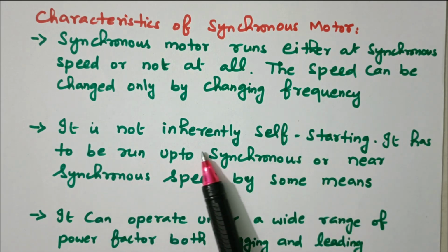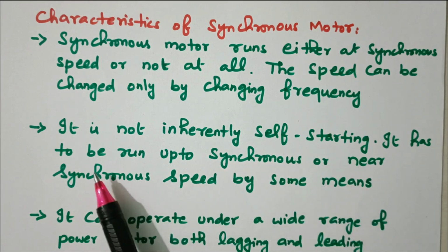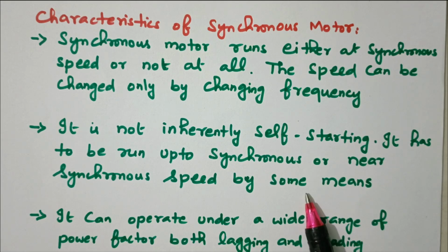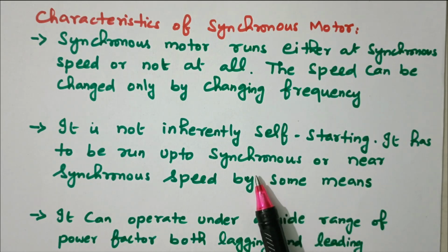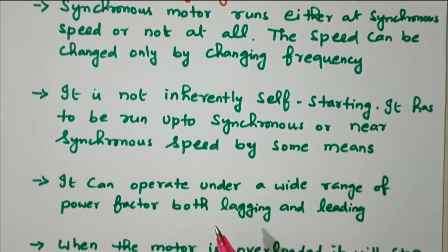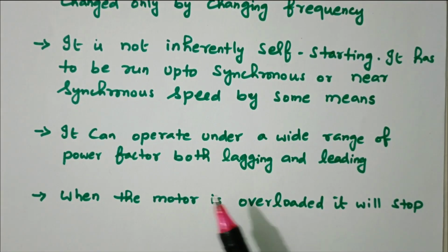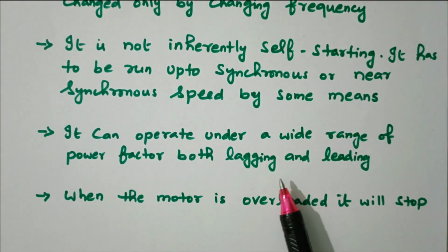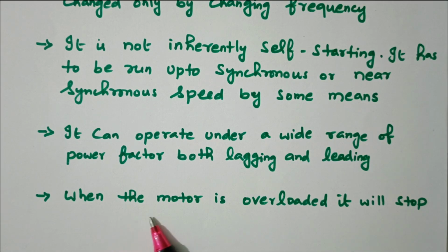It is not inherently self-starting. It has to be run up to synchronous or near synchronous speed by some means. By having some other arrangement, we need to rotate the machine up to synchronous speed. It can operate under a wide range of power factor, both lagging and leading. Both lagging and leading we can operate the motor. When the motor is overloaded, it will stop. If it is overloaded, it will not rotate, it will stop.